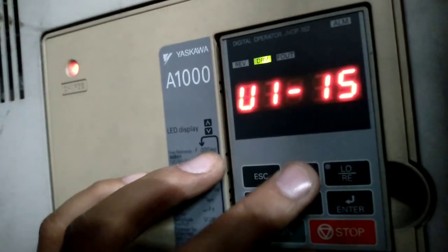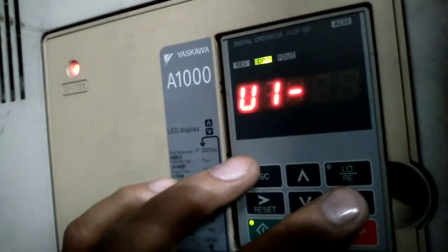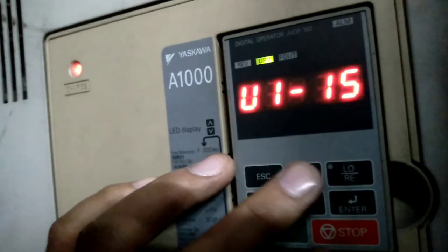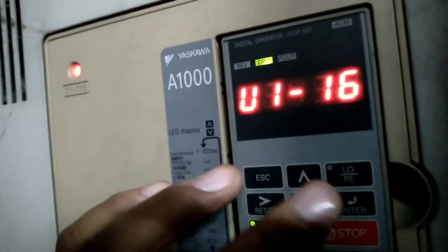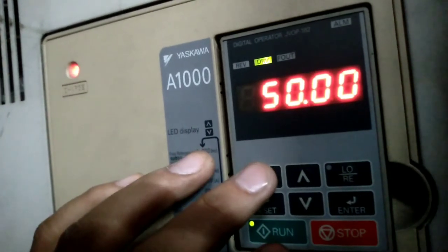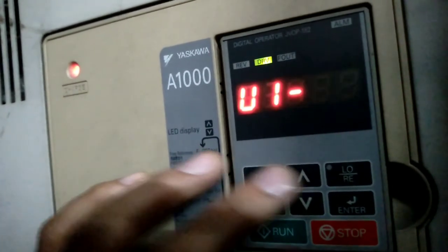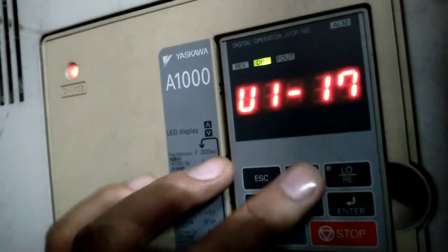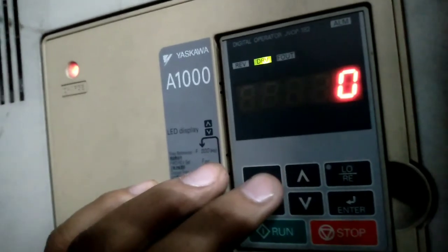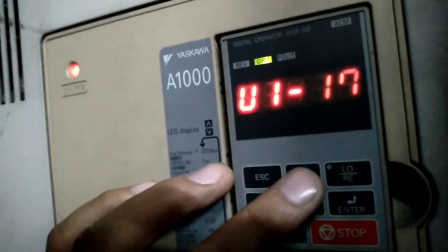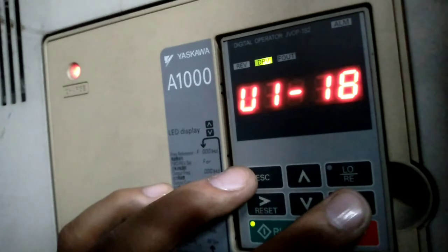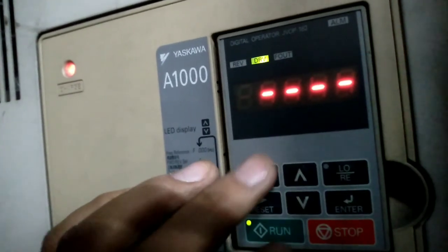In this kind of situation, it is very important to access these monitor parameters and to monitor the running amperes, terminal voltage, DC link voltage, heatsink temperature, motor temperature. All these things are very important, where you could easily troubleshoot the reason because of which the drive is tripping. So these are the parameters in the monitor menu.